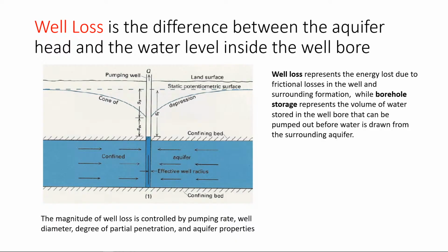But another thing other than the well loss, yeah, is borehole storage. So what is borehole storage? Borehole storage is the volume of water that's stored in your well bore. So here in your well bore, you will find that water is already stored. This water is not coming from the aquifer. This is just coming from your borehole. And this can be pumped out before you draw water from the surrounding aquifer.